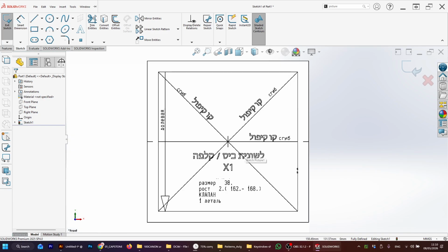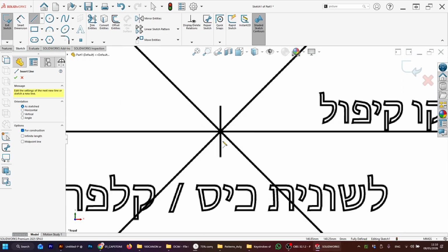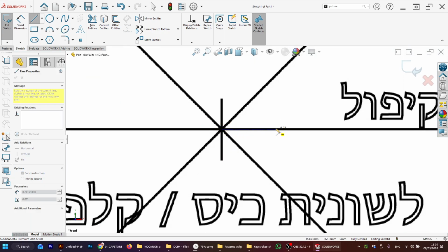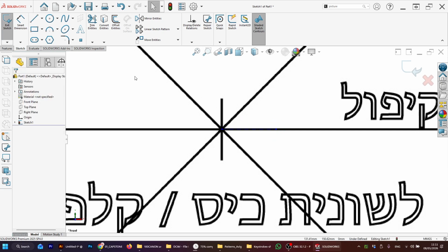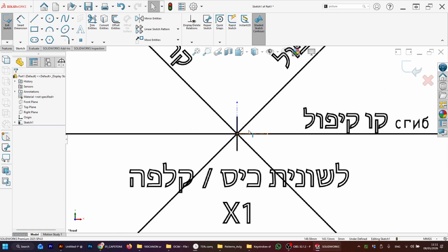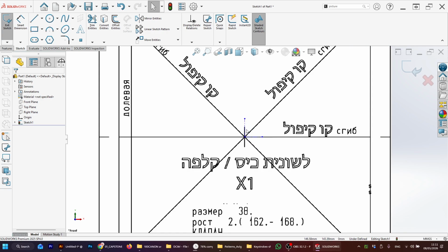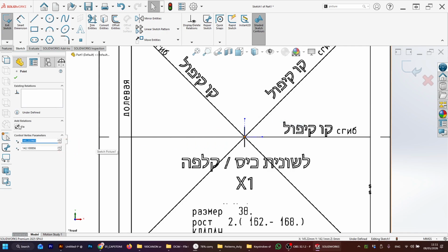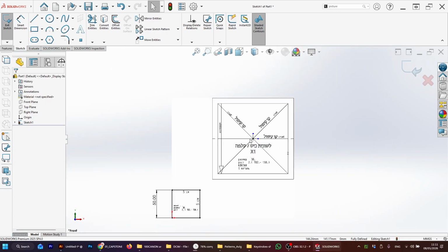If I want an alternative way that is similar to the logic that was used to sketch this, close to the line I have a little arrow. When I click on it, I can choose center line. Center lines are lines that help me sketch. I put one here, escape, I go back to the line, one here, and now I have exactly the center of this shape. I can click on the dot and ask it to fix. This way that dot cannot move. I can't make mistakes. I can't move things by chance.